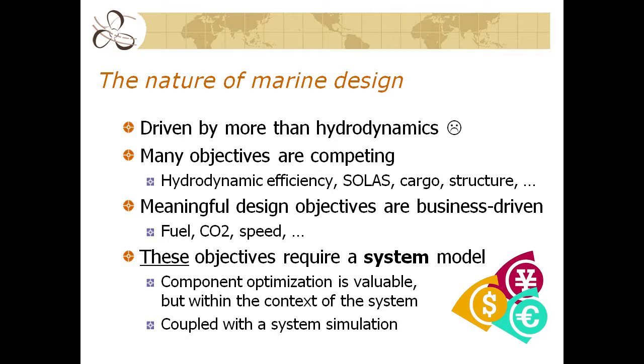That's the objective here. Fuel, regulatory issues like CO2 production, emissions, EEDI, some of these kinds of things that we're seeing is an important part of the business plan. We have to meet those regulatory requirements, but they have nothing to do about the optimization or the individual analytical setting. The meaningful design objectives are business decisions. And those business decisions are not about individual pieces, they're about the system. So the system model that we want to hit on, that I mentioned earlier, the Hull-Propeller-Drive-Engine system, is where this whole story has to start.